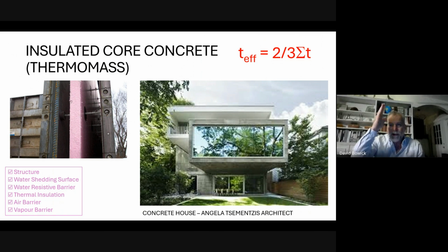A lot of it is deflected, runs down the face because it's a water shedding surface. Some portion of that water is absorbed into the concrete, and it's just absorbed and stored there until the relative humidity outside drops down to the point where the water can dry, and then it simply dries.